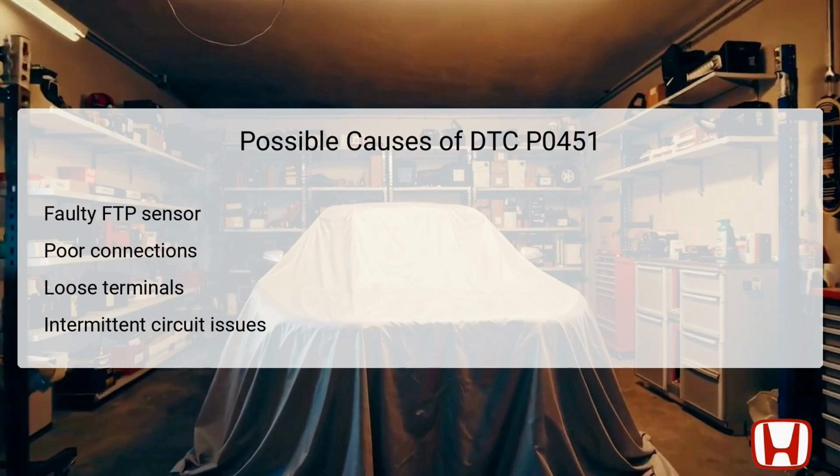Several possible causes may lead to the activation of DTC P0451. A faulty FTP sensor is a primary suspect, as it may fail to provide accurate readings due to internal damage or wear. Poor electrical connections can also be problematic, affecting the signal transmitted to the ECM.